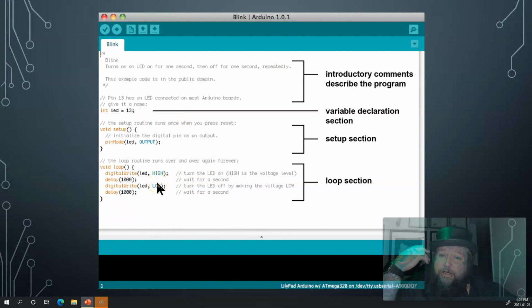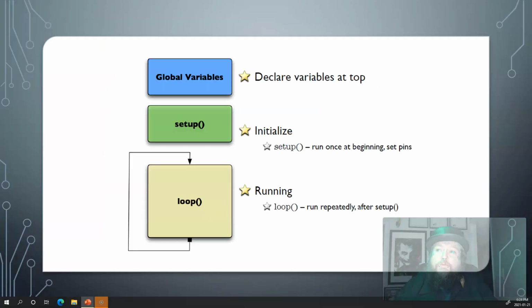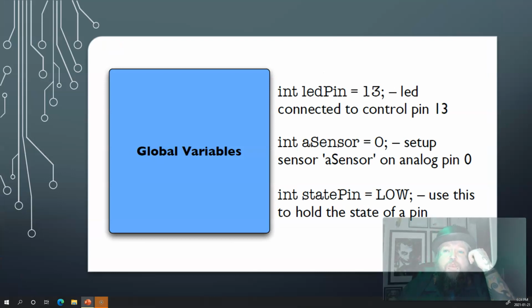And this sounds weird, but it's going to be important to get into your head to not think of this like a main where you try to do everything, like robot do this, then this, then this, and by the end the program shuts down. Well, no, you want to take advantage of it constantly doing this controlled loop, the robot control loop cycle, sense, think, act, and taking advantage of that to get your closed loop kind of control.